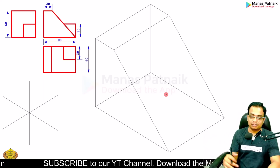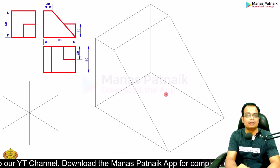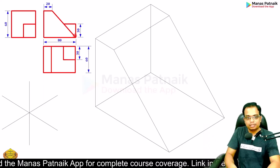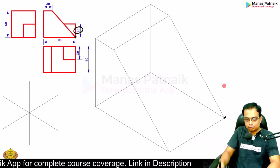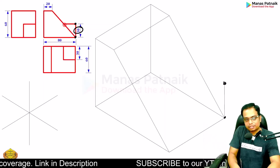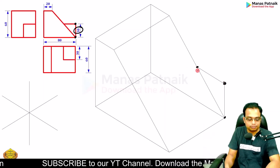Okay. In fact, the first problem on isometry, the question number 5, was way tougher, right? But again, you always need to select the easiest option. Okay, good to go. Now you see this. Yes sir, what is the height? Sir, it is 30 millimeters, so 30 millimeters, and then you are here. Produce a line in this direction in the isometric until it intersects this slant edge, somewhere here. We are good to go.